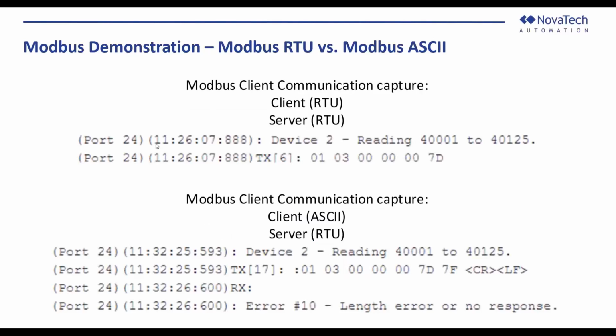So Modbus RTU, we'll consider that in the present day to be much more common, so much as to say it's pretty much exclusive that you'll find Modbus RTU on modern devices as opposed to ASCII. And the Modbus RTU will send data just as straight binary characters. It doesn't do any sort of manipulation of those. It doesn't change the way it's presented. By contrast, the Modbus ASCII is less common, and it's also less efficient with data, and I'll explain why here in just a second.